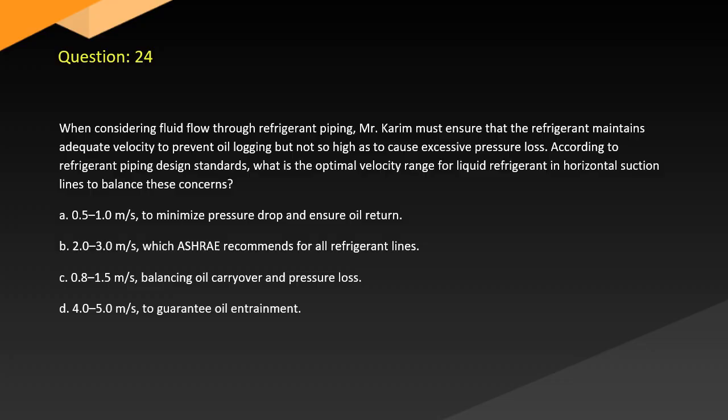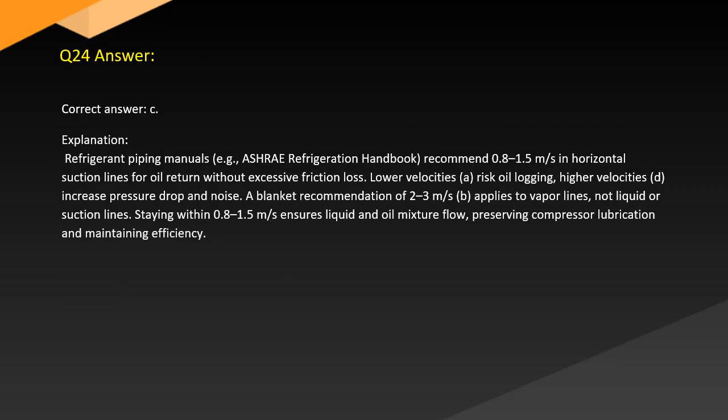B. 2 to 3 meters per second, which ASHRAE recommends for all refrigerant lines. C. 0.8 to 1.5 meters per second, balancing oil carryover and pressure loss. D. 4 to 5 meters per second to guarantee oil entrainment. Answer. Correct answer: C. Explanation.